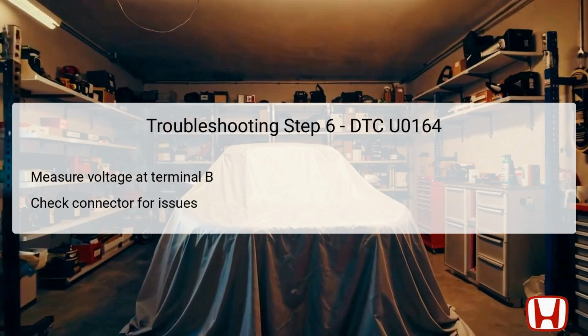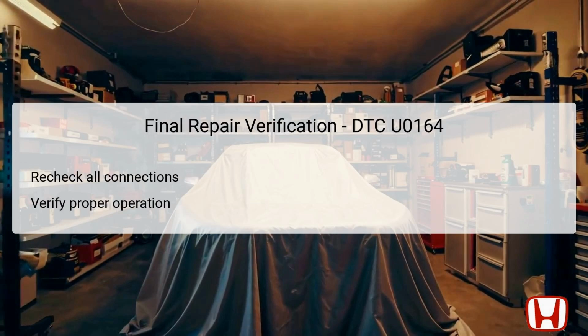The final repair verification step is crucial in ensuring that the issue associated with DTC U0164 has been completely resolved. This involves rechecking all connections made during the troubleshooting process, including ensuring that all terminals are seated properly and that no corrosion or physical damage is present.